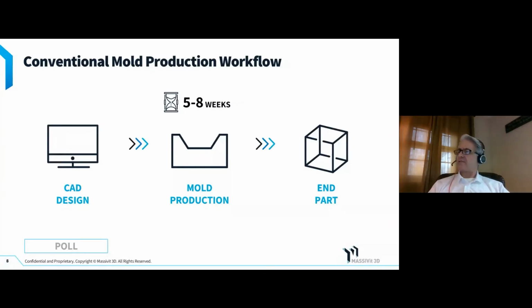So that is in line with what we've seen in the industry. And if it's less than 2 weeks, typically it's either a very small mold that you can make from an existing part, so you're not even making the master tool. You're maybe splashing it off of an existing part, or you're CNCing something and you don't have a large queue in your CNC department.